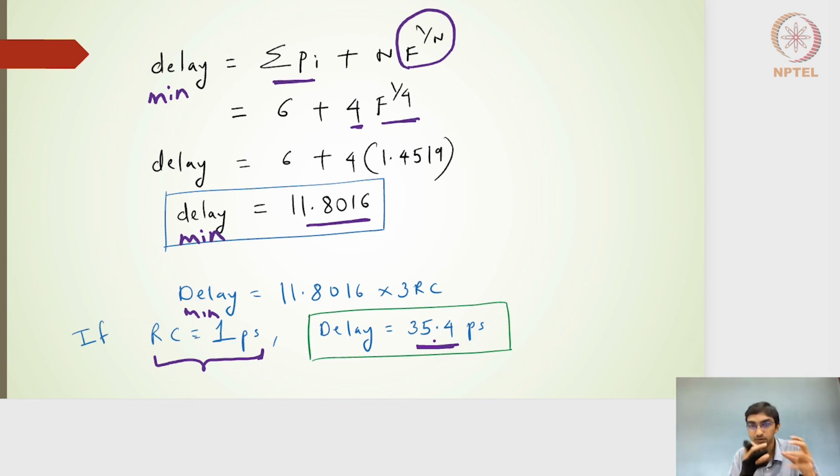Then using that notation, we applied the linear delay model, and for a single path, whatever the number of stages, we were able to estimate the optimum x, y, and z values so that the overall delay turns out to be minimum. Remember that what we identified is the optimum sizes of the gates. Once we identified those, we were able to distribute and allocate the optimum width to the individual transistors.